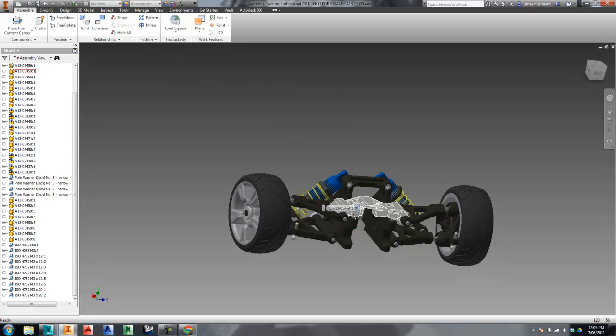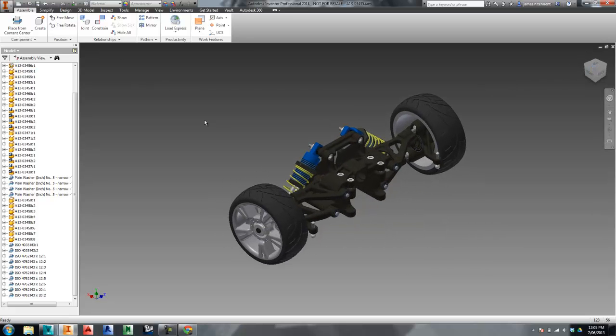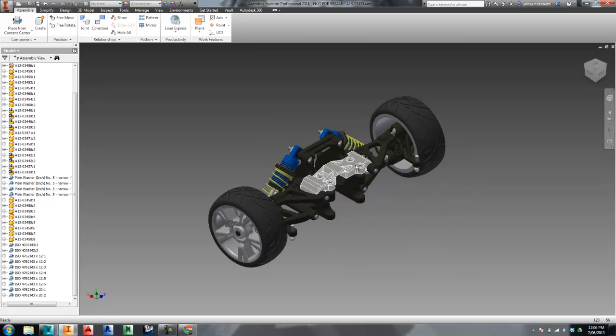Hitting the refresh button will send that component back to its normal position. Actually, I should say update button, and those constraint visibilities will be turned off. So really nice way of doing your modeling and at least interrogating your model to find out how something was put together and how to resolve those 6 constraints.